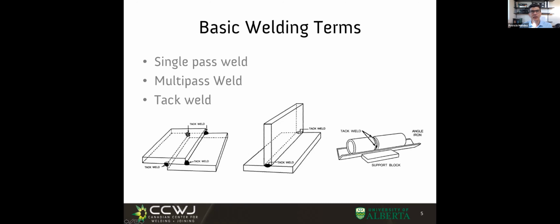And why this matters, because as we weld, and we're going to have 1 or 2 lectures on this, the thermal expansion creates distortion, so everything moves. If you don't want it to move too much, you have to clamp it very much. Sometimes you tack it, right? And again, this is such an important concept.